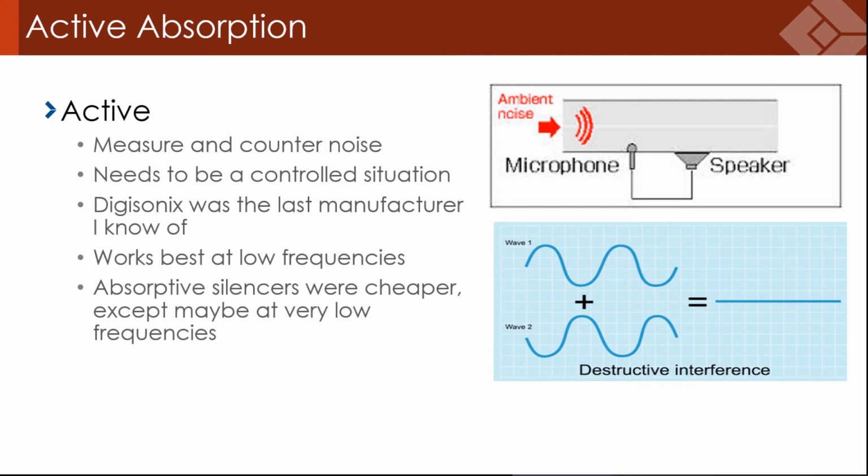I think the issue is the noise has to be pointed in the same direction. And down a ductwork with liner in it, I think that's pretty easy to do. Down a normal duct or in an exhaust stack, it can be tough. And there are temperature limitations too. I tried to do one on a 2,000-degree exhaust stack from a natural gas power generation unit, and they said they didn't have speakers that could handle that kind of temperature. But maybe some companies will get back into that business and will have some ability to do that.